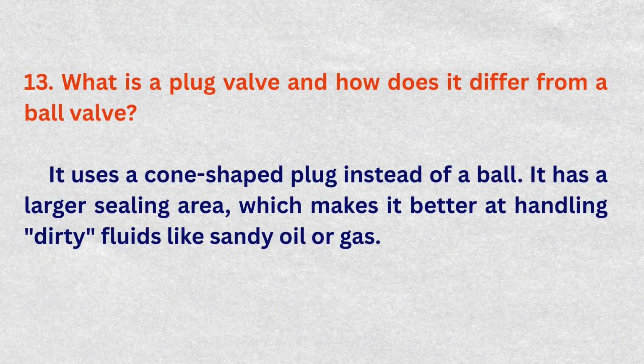What is a plug valve and how does it differ from a ball valve? It uses a cone-shaped plug instead of a ball. It has a larger sealing area, which makes it better at handling dirty fluids like sandy oil or gas.